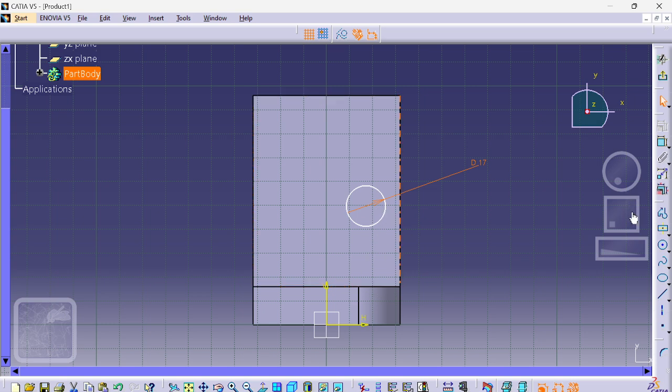So double click over this constraint, blue box, okay, command, and click over the center of your circle and then click over this edge. So it will create the dimension in between that. Okay. Again, similarly, center and this particular vertical edge, it will create another dimension.